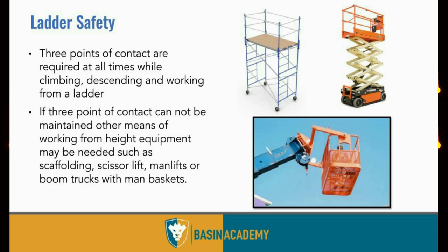More about ladder safety. 3 points of contact are required at all times while climbing, descending, and working from a ladder. If 3 points of contact cannot be maintained, other means of working from height equipment may be needed, such as scaffolding, scissor lift, man lifts, or boom trucks with man baskets.